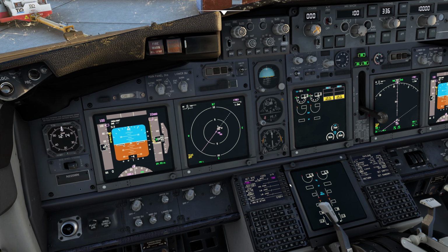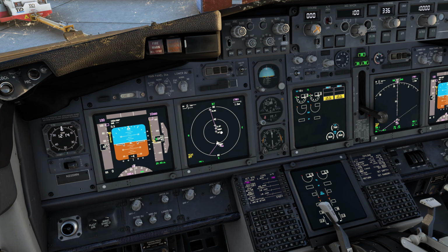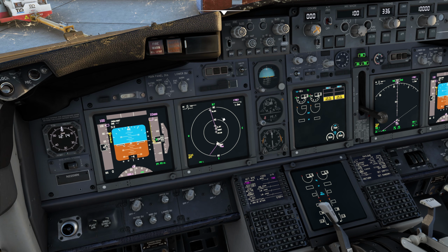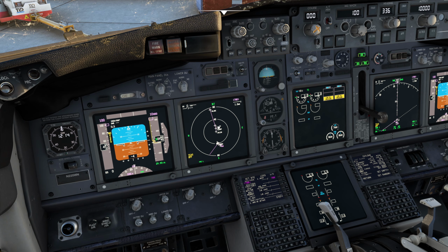And if you watch, when I click step here, let me zoom out a little bit. When I click step here, what it's going to do is jump through the waypoints. So here's that WESLYN waypoint, Mont, Killjoy, Magic. You can see that same departure north out of Houston. It'll step through every single waypoint throughout the flight plan, and you can verify that everything looks good on your